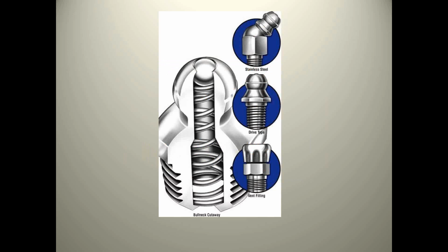Talking about lubing, now that you know how small these particles actually are, how many particles can I get around this little groove of this grease zerk? If you're talking about 40 micron particles, let's say we can get 100 of them around there. Well, every week or every month we do the lube task, those particles get pushed into the bearing. So we have to have procedures in place with our maintenance people to keep particles off this ball, keep a little bit of clean grease over the top of this so particles can't get to the ball, or we can use those fancy colored caps to keep our grease zerks clean. But again, a good training session for maintenance people, making them aware that the particles are so small that we're going to pump those into our components every week.